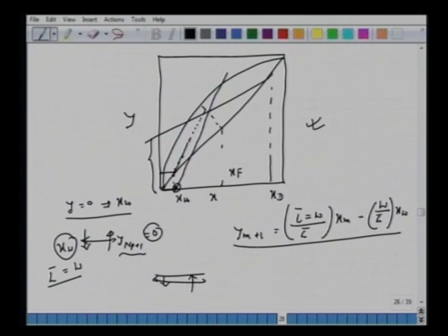Alright. Now again, you should go back and carefully see that this open system, or open steam system, whatever we're calling it here, is nothing new. New in the sense that our approach remains the same. You write down the operating balance equations or species balance equation for this bottom envelope, the section underneath the feed, to realize that there is a modification in the overall material balance, and there is a modification in the species balance for this stripping section here. And then the modification comes from the realization that we don't have a reboiler.